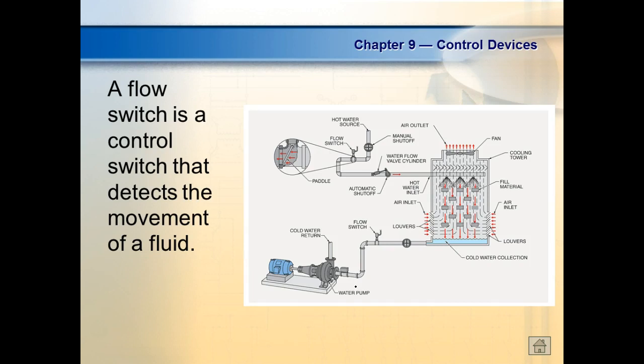They just put a vane down inside the flow. They seal it up real good, put a spring on it. Water fluid comes through, pushes against the vane, makes the outside move, and they flip the switch when it gets up to a certain level. Now we have flow sensors. It's hard to get a sense of flow, but we have different types of flow sensors that we can use. But a vane is probably one of the most popular used on a flow switch.